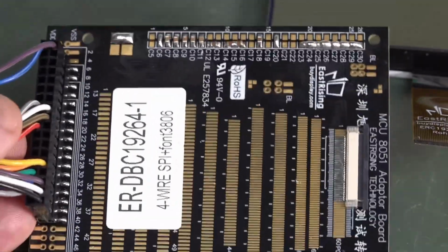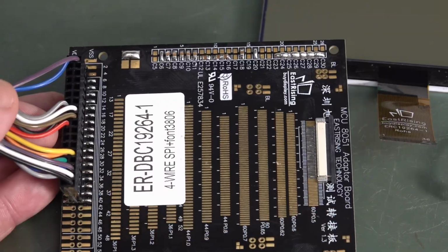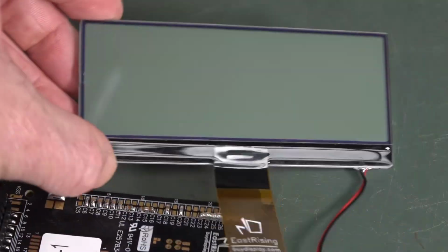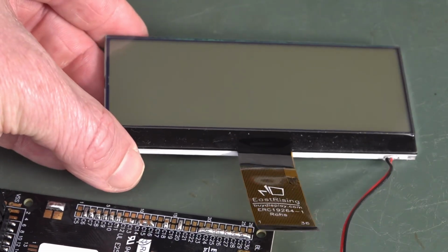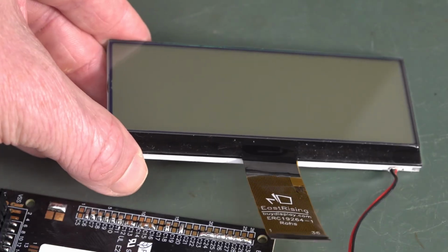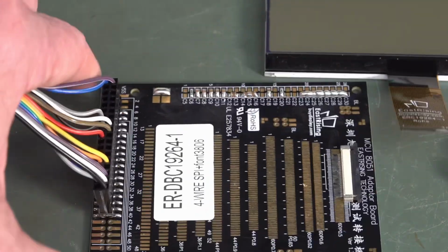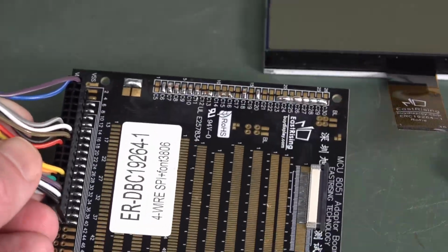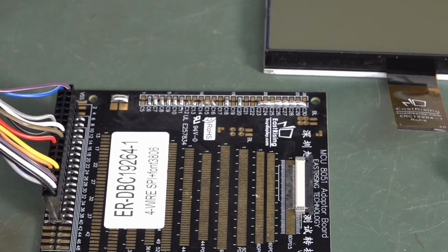I haven't gone through the exact pinout of this thing. They're only using some of the pins here. I think I specified an SPI interface because this LCD is capable of SPI serial interface. I think it might do I2C as well as 4-bit and 8-bit parallel interfaces. So it's very flexible, but I think it might be working serial, but I haven't 100% confirmed that. Anyway, let's plug it in and see if we can get this thing working straight out of the box.